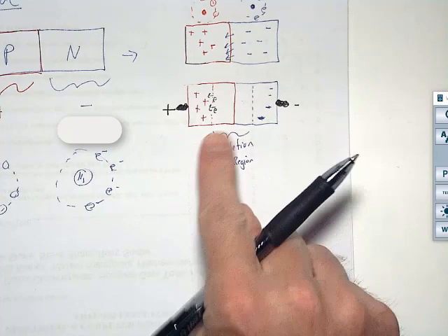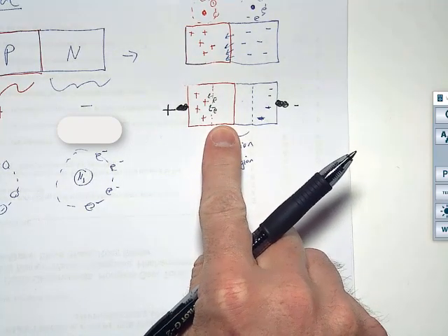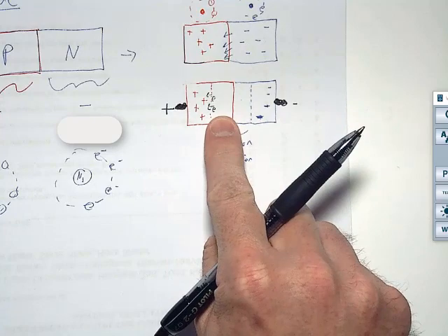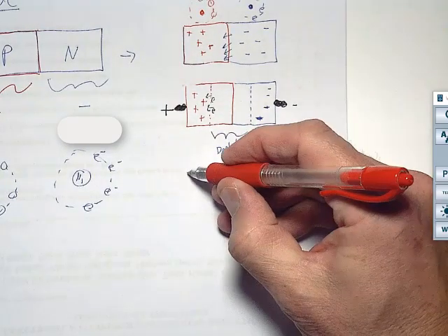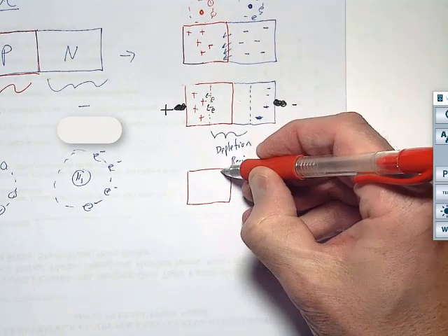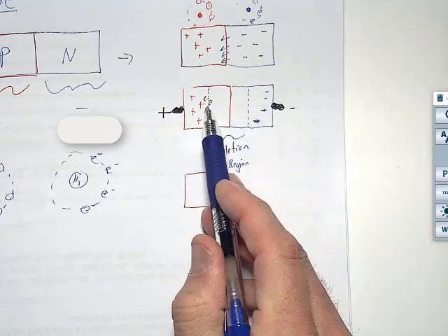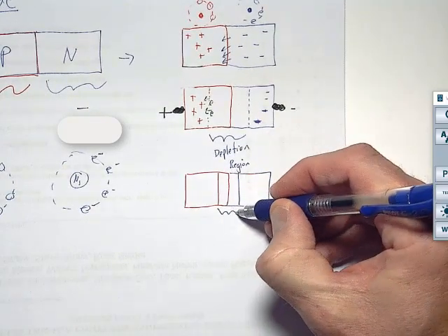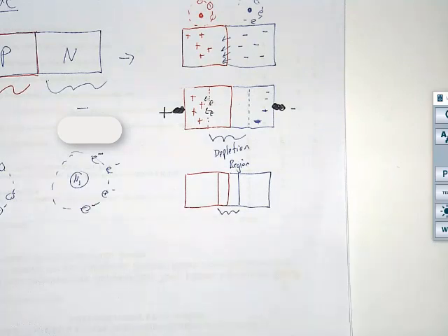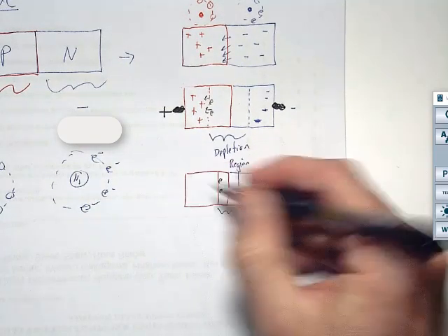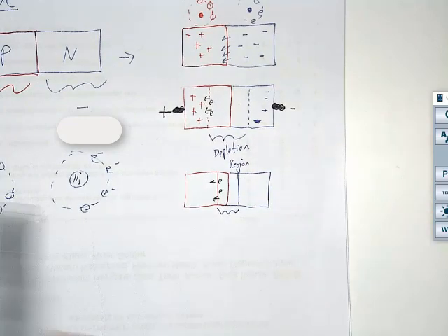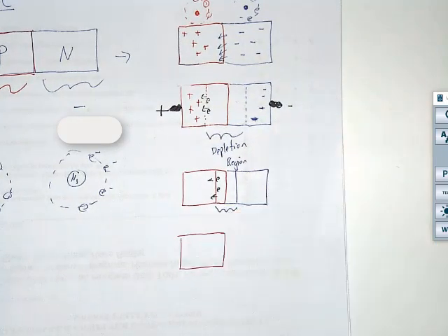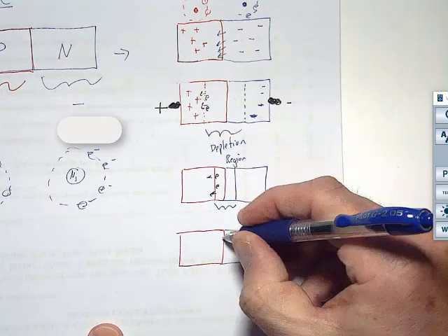Now what happens as the electrons go away? This region then becomes positive again. So what happens is that that depletion region actually starts to shrink a little bit. Okay? Because these electrons are getting pulled over, and then the same thing happens over here where this region gets a little bit smaller, and it's because these electrons keep getting pulled out of that little region right there as we have this voltage, and they're heading out of there, and then it keeps going and going and going. And ultimately, you will get to a situation where you have that same PN junction, except there is no depletion region.